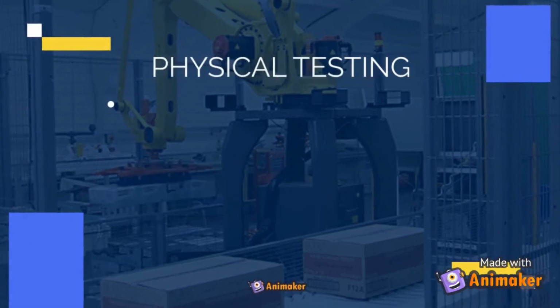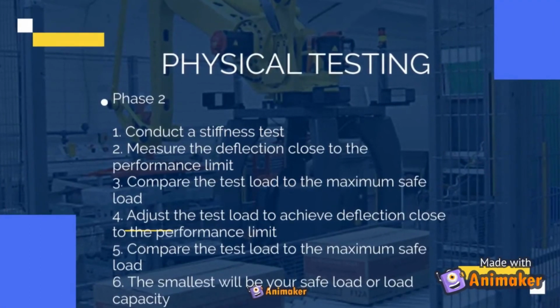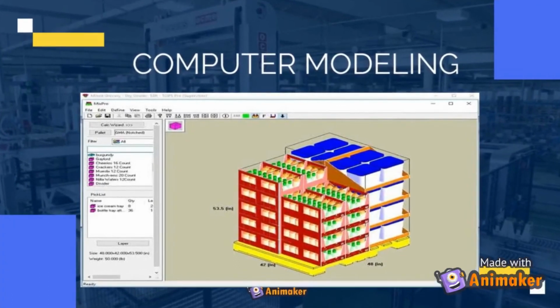For Phase 2, conduct a stiffness test, measure the deflection close to the performance limit, compare the test load to the maximum safe load, adjust the test load to achieve deflection close to the performance limit, compare the test load to the maximum safe load, and the smallest will be your safe load or load capacity. Next, this is one of the examples of computer modeling. You can see the example based on the diagram shown.